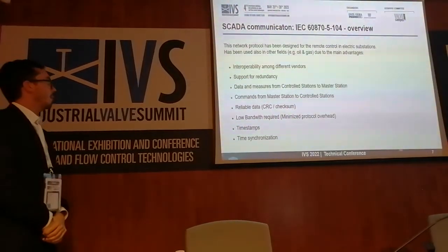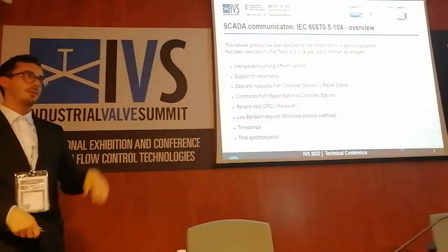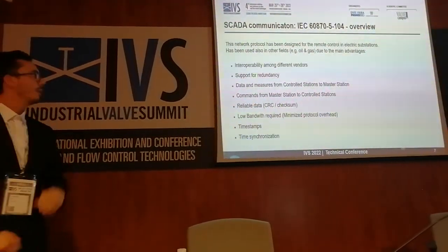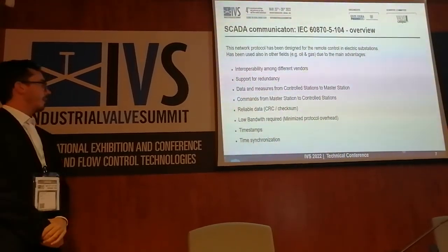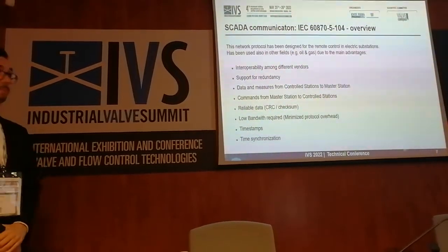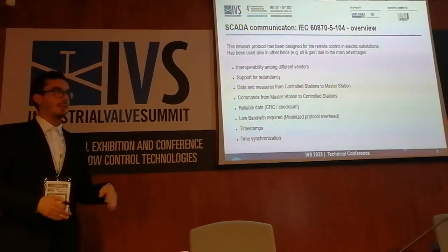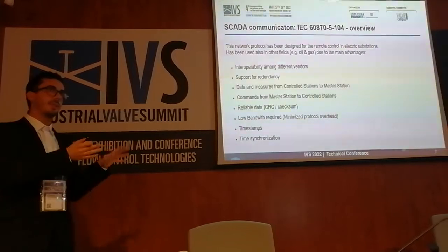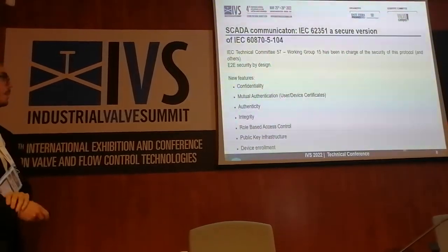And it's possible to provide data and measurements, so the flow of information goes to the SCADA as well as the commands from the SCADA to the control systems. And there are checksums and this kind of reliable data information. It uses low bandwidth and provides information with timestamp. So for example, if some digital input moves, the information of when it moved is inside the protocol itself, as well as for time synchronization.